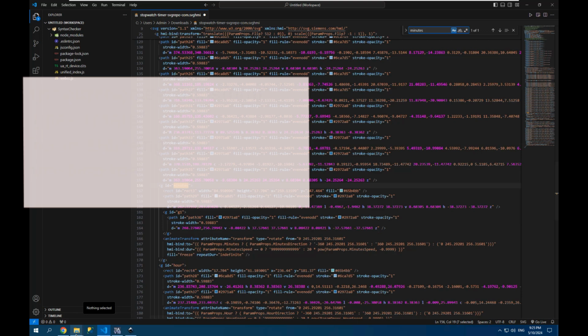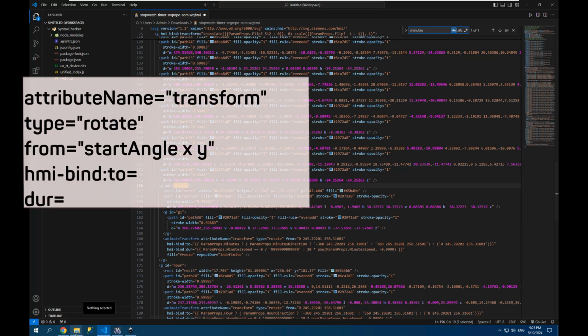And the last important parameter, duration of animation. It is set in seconds, and accordingly, the shorter the time, the faster the arrow will rotate. Here too there is a little logic. If the speed is set to 0%, then the animation time will be 9999 and so on.